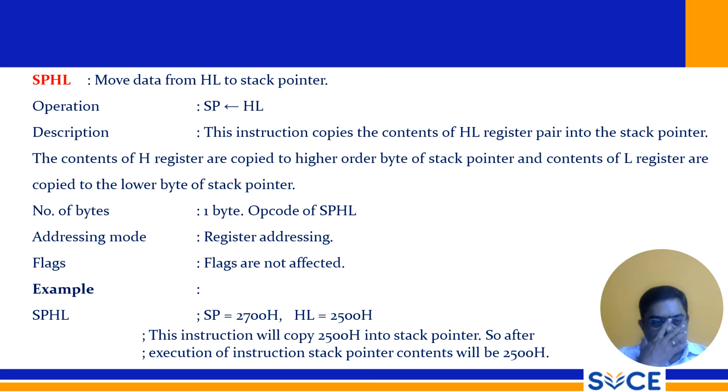SPHL moves data from HL to the stack pointer, HL to stack pointer. It is a 1 byte instruction. It comes under register addressing mode. Flags are not affected.